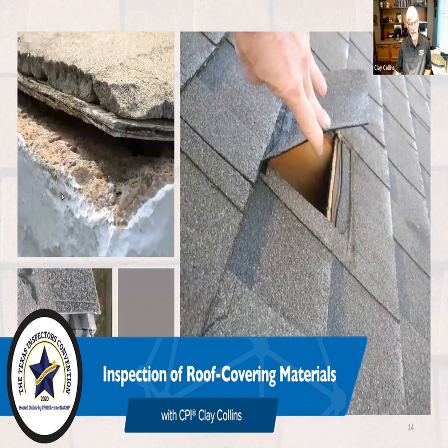And I'll show some pictures in a little while that show, with the loss of shingles there at the hip, you can see what caused the leak after the loss of shingle. You can lose the shingle, and if your underlayment's installed correctly, you shouldn't necessarily have a problem. If they installed the underlayment correctly, you're less likely to.